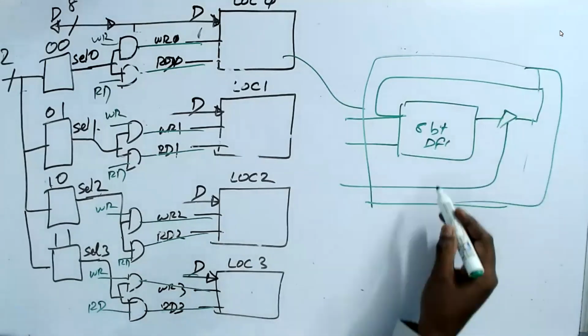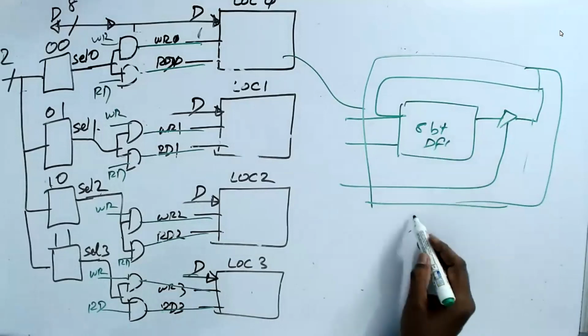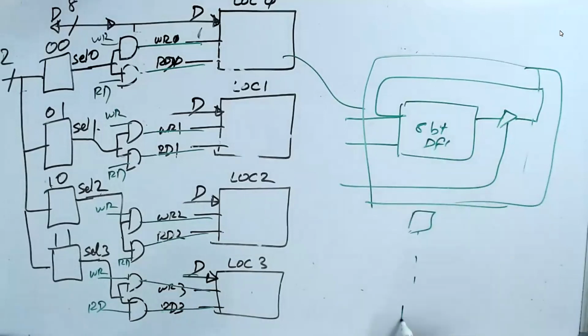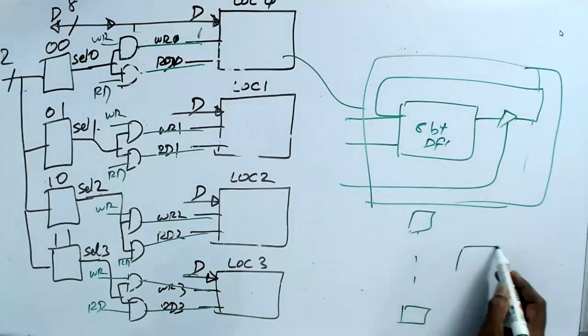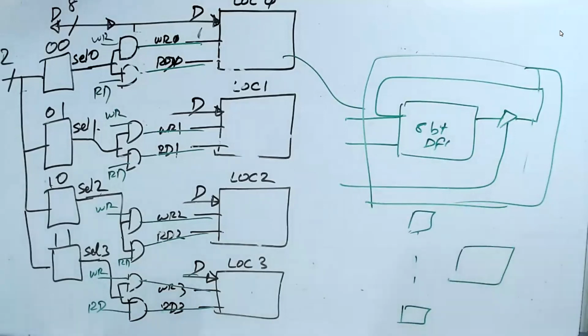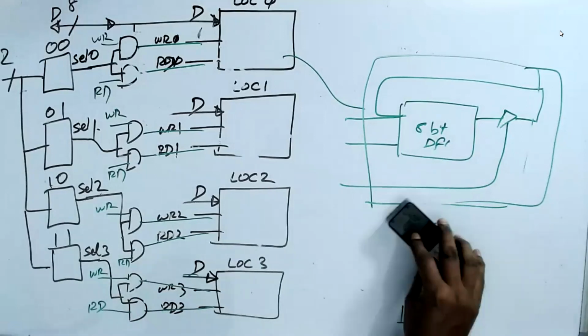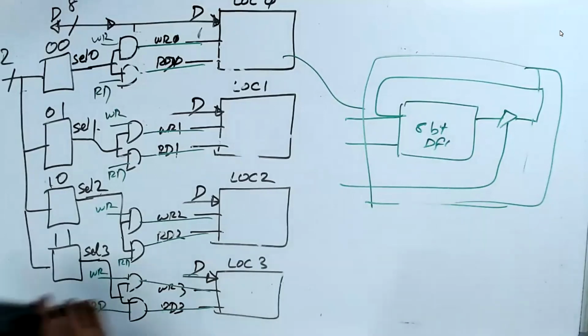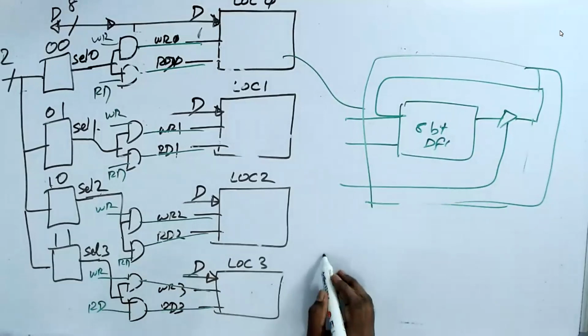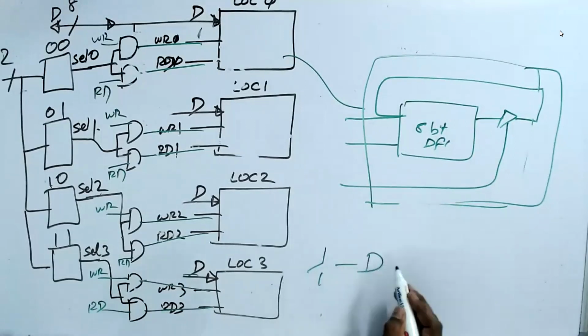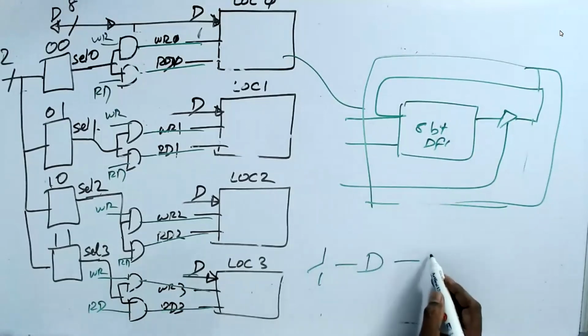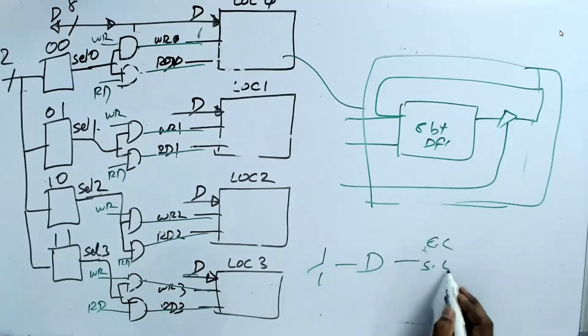And if you take a 1-bit D, this has 8 D flip-flops. If you take 1 D flip-flop, that has so many gates inside. So that means we are making building blocks. How are we making a building block? From switch, we form gate. From gate, we formed combinational logic, sequential logic, and tri-state logic.